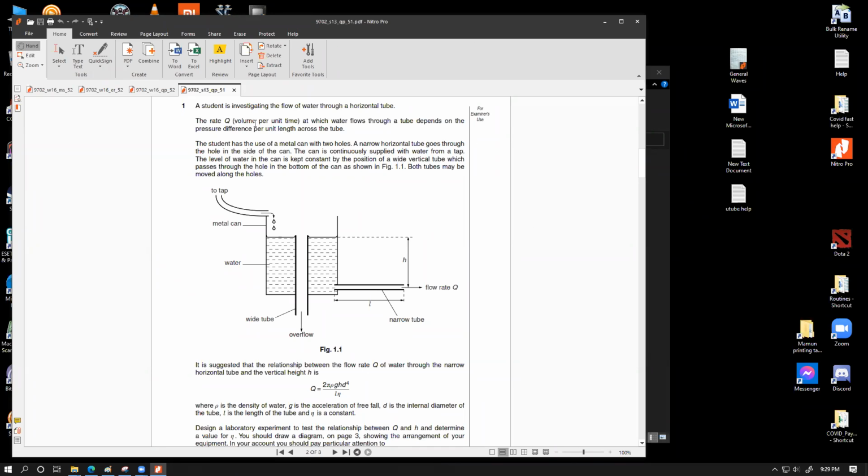Acha. The idea is that you place a large enough bucket in front of this channel. Then, as you allow the water to flow through the horizontal narrow tube, you start the stopwatch and allow the bucket to fill up for the duration of the time. And the moment you stop your observation, you stop the stopwatch and remove that bucket immediately.